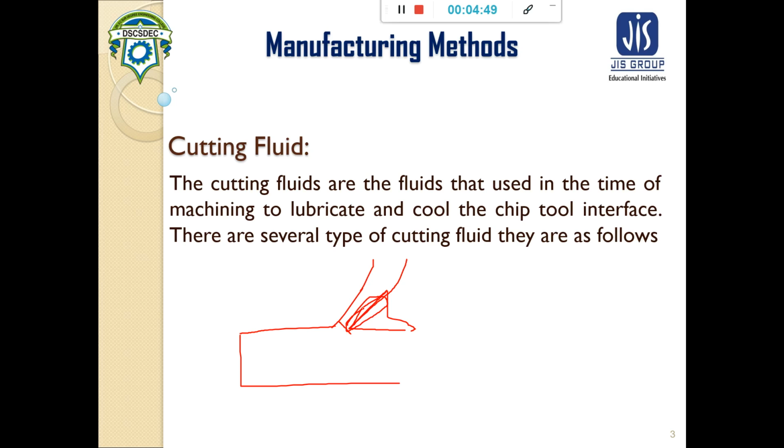So the heat generation will also be less, and the ceramic materials can withstand a high amount of heat. Due to all of this, in the case of ceramic, dry machining is advised.